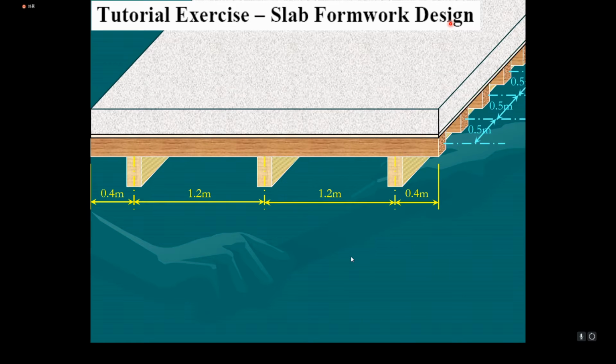Part C is related to Part B. So in Part B, you calculated the maximum bending moment and maximum shear force on the joist. And then you can compare the maximum values with the allowable value. So depends on the size of the joist which is given to you, and the strength class C16 in part C, you can look up a relevant table for the allowable values, moment of resistance as well as shear load.